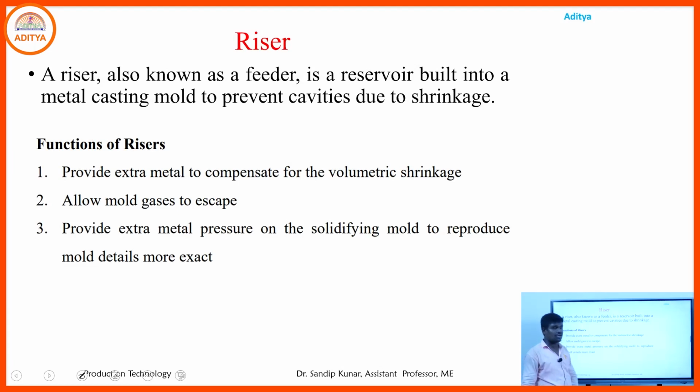What is the riser? I have already told you, a riser is a liquid metal reservoir, which also acts as a feeder system. In that system the extra metal will be stored. When shrinkage takes place in the casting product in the mold cavity, at that time the extra metal is fed to the mold cavity to compensate for the material.